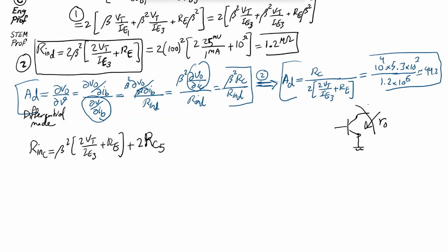In this case, RO is the well-known early voltage of the BJT from the early effect divided by, roughly, the emitter or collector current, DC. And that's coming from the IV curve of the BJT. This is the current of the collector or emitter, which is roughly the same as the current of the emitter for large enough beta, which is the case here, divided by the collector-emitter voltage.